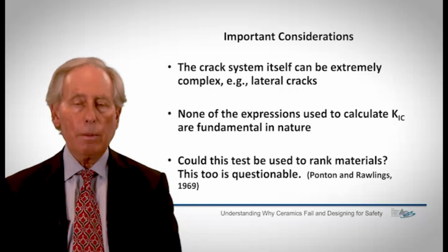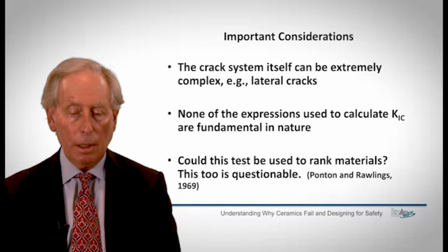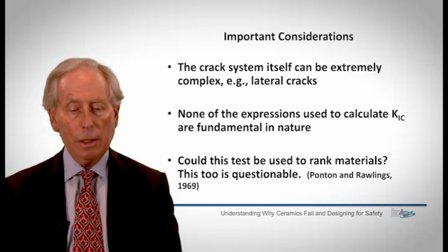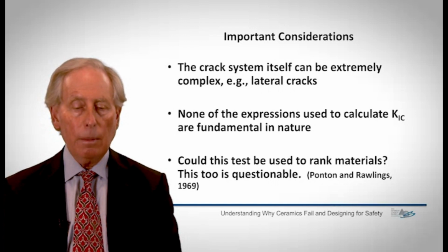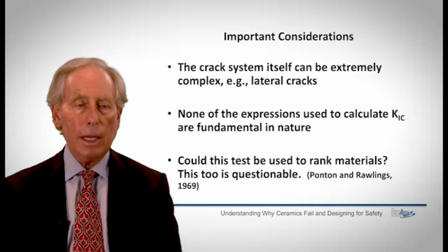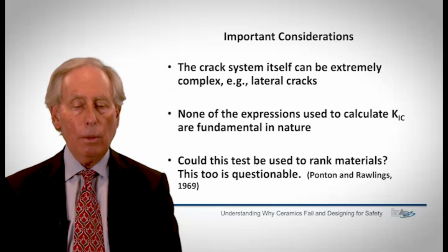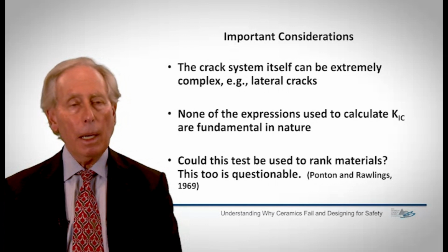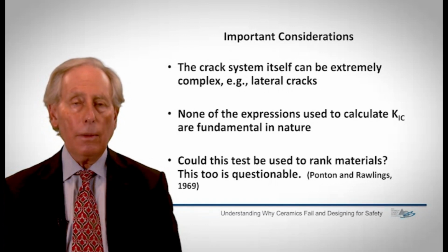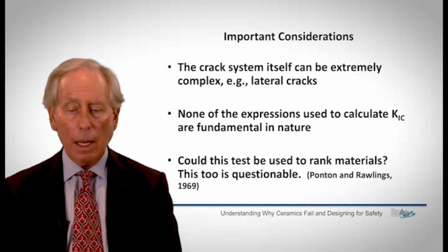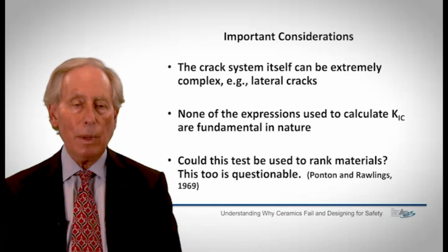They can interfere with my calculation of the fracture toughness from this particular technique. There are many expressions to calculate K1C from this kind of procedure. The one I showed on the slide a few minutes ago is probably the most accurate, but it turns out that they're not consistent with one another. Every one of these expressions will give you a different value for fracture toughness.